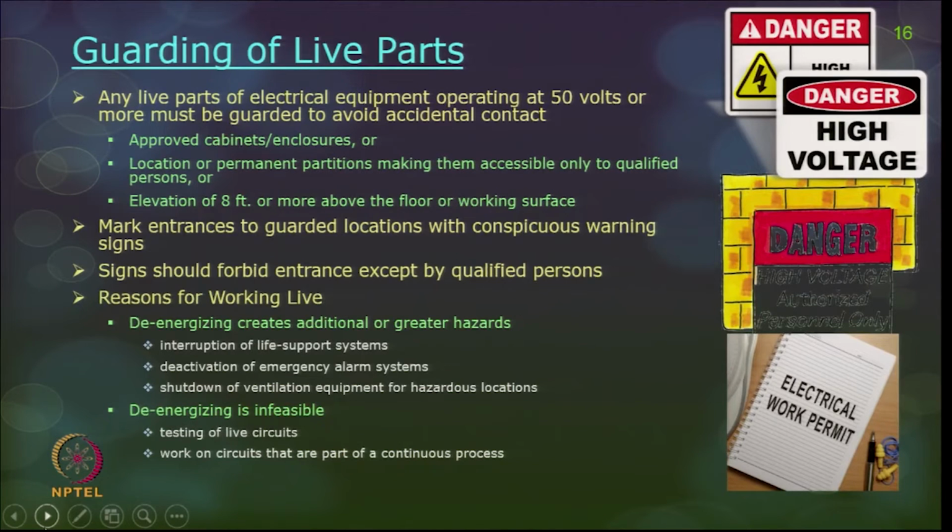The next hazard is guarding of live parts. Most of the times, workers have to work along with the construction equipment for repairing or for maintenance when the power is on. Okay, there are situations that will arise. So, how do you take care of working with live wires or live parts and also guarding of those live parts? Any live parts of electrical equipment operating at 50 volts or more must be guarded to avoid